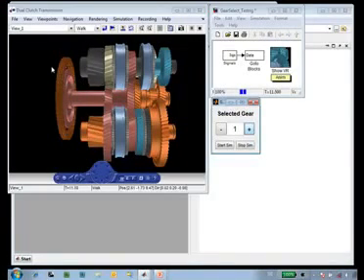The flow of power is highlighted in orange, so you can see that the flow of power goes through the clutch for the odd gears plus reverse to this shaft, which is connected to the odd gears and the reverse gear, through gear 1 to the dog clutch, which is connected to the output shaft, and then this connects to the rest of the drivetrain to the wheels. As we move up the gears, again on the half gear, the dog clutch engages the next gear to which the transmission will shift, and then on the full gear, the input clutches change state.